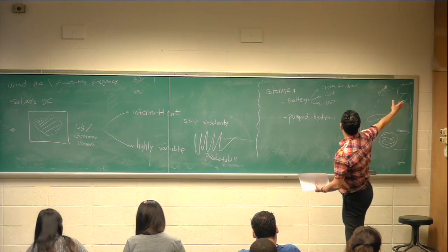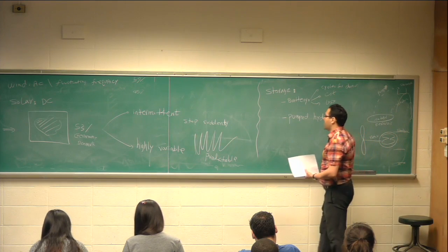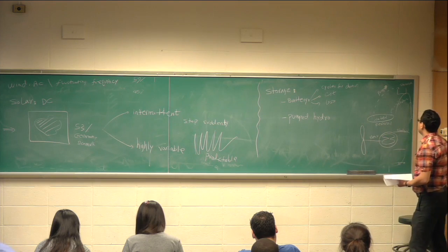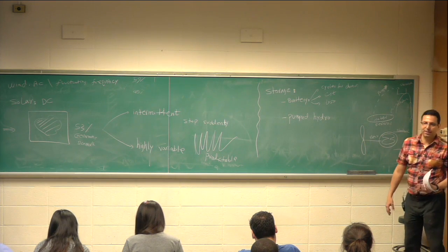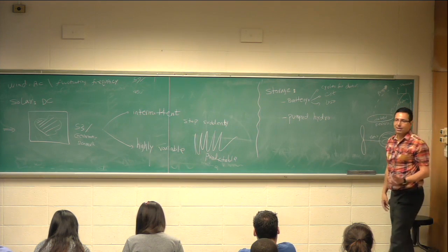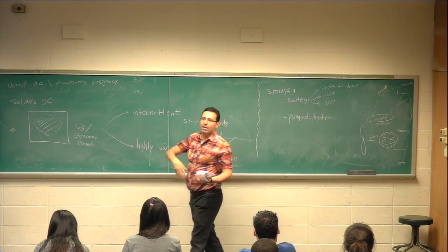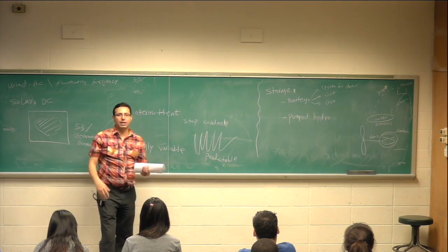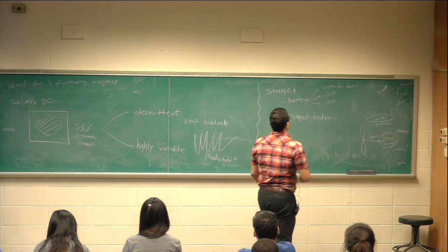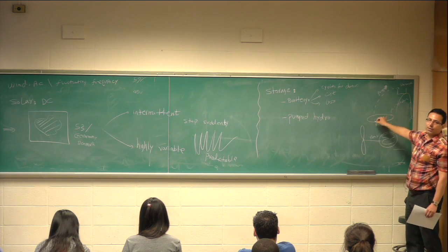And this is how people in Montreal, Vancouver, a lot of places in Canada get energy. That's why their energy is really cheap. And in places like Switzerland and Germany, one country has a lot of water, one country has mountains. During the day, they ship water. During the night, they take it back. So that's how they deal with this. It's not the case that you have all natural resources in the same place. So pump hydro is very efficient, but you need natural resources. You need water and mountain at the same time.